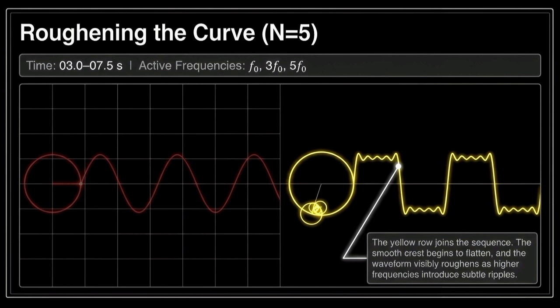Okay, that makes sense. Now think about pure destructive interference. Right at the very top of our original smooth red wave, like the absolute peak of the fundamental, these smaller, faster, odd harmonics are mathematically dipping down. Wait, really? Yeah. Their valleys are aligning perfectly with the fundamental's peak. Oh, wow. So they are actively subtracting amplitude right where the fundamental is trying to be at its absolute tallest. Exactly. They are literally squashing the peak flat. Yes, they are mathematically carving the peak down through destructive interference.